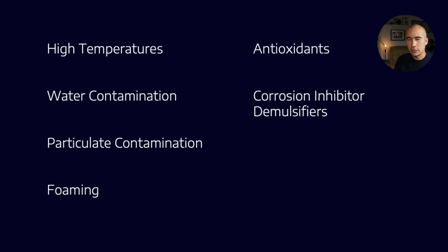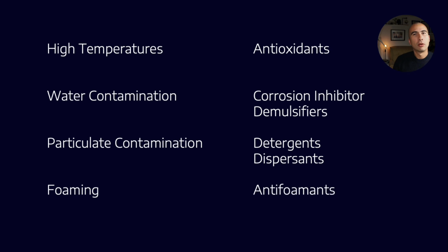Then we've got particulate contamination. Well, to deal with those, we have to use detergents or dispersant systems. And finally, with foam, really all we have, aside from increasing the residence time in our reservoir, is to use antifoamants. And these are usually polymethacrylates, or they might be silicon antifoamants.